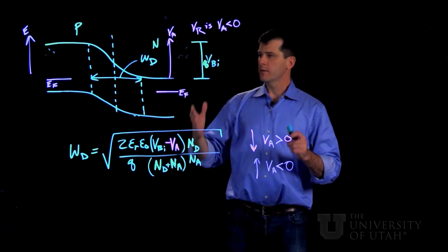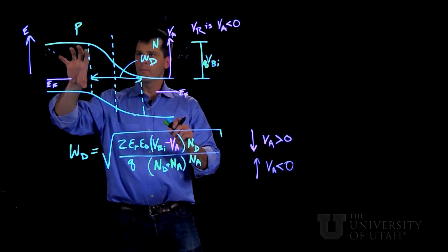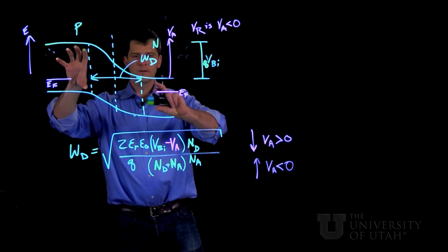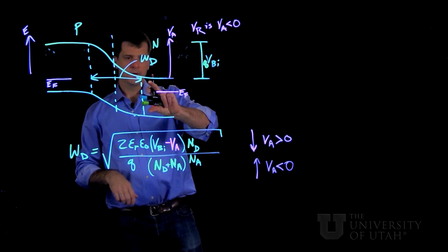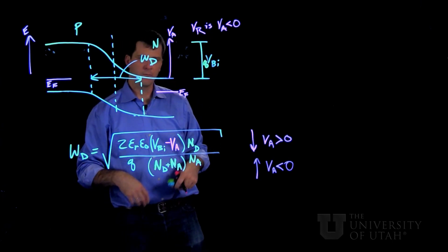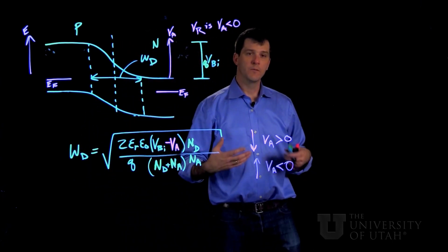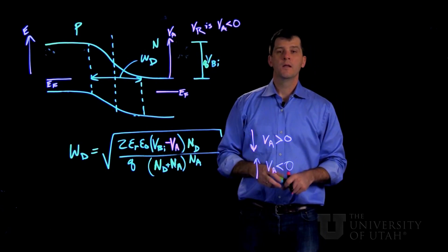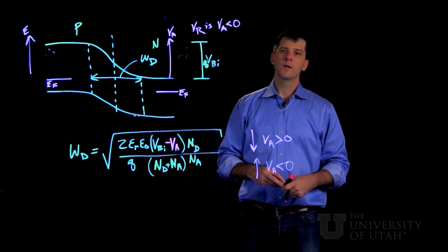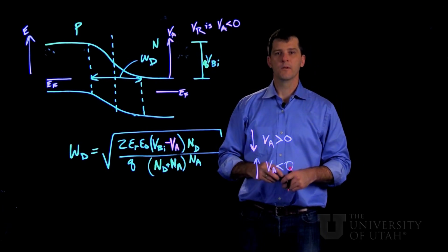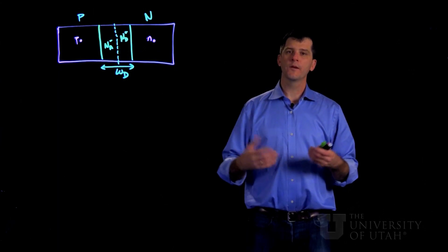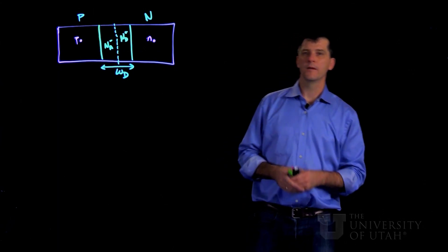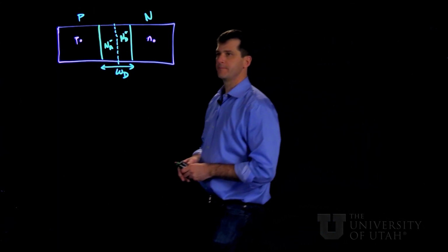So now let's look at the consequence of the fact that we have a situation where we have a conductive material here separated by a dielectric insulator here with another conductive material here. We can model this almost like a parallel plate capacitor, and thus the junction has some capacitance and can be used to give capacitance in circuits. So now let's take a look at the capacitance inside a PN junction.